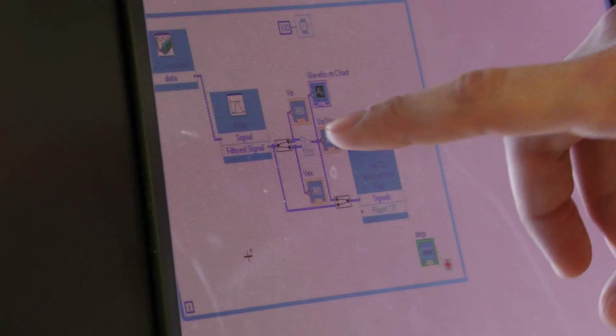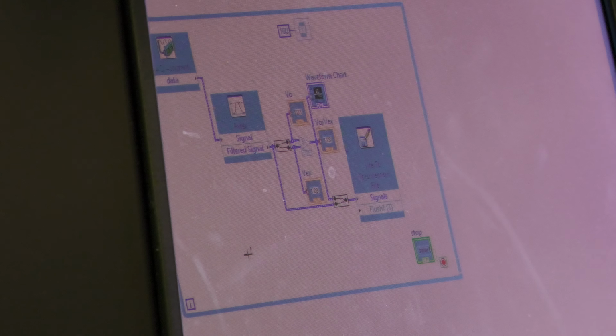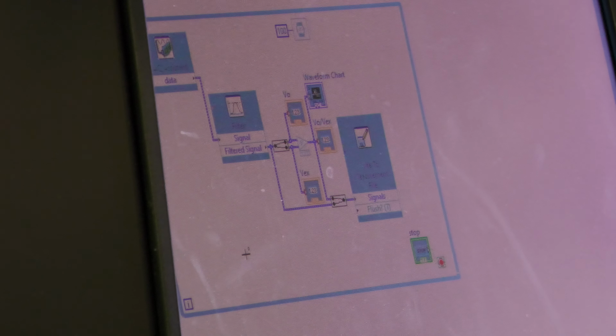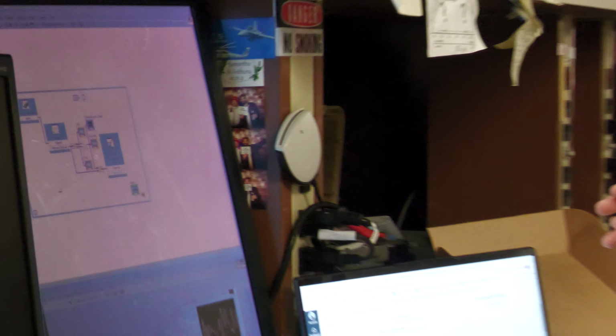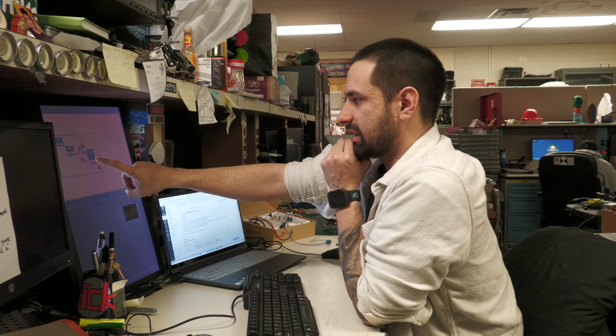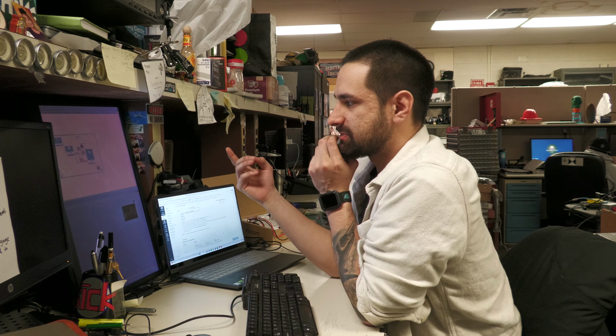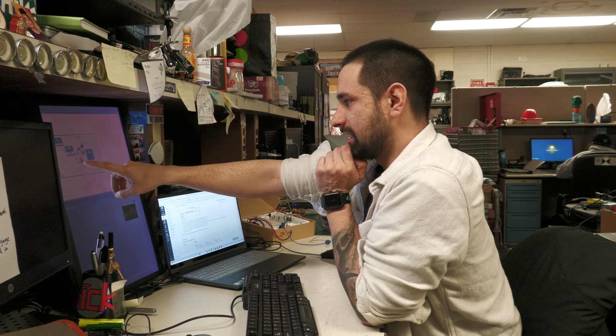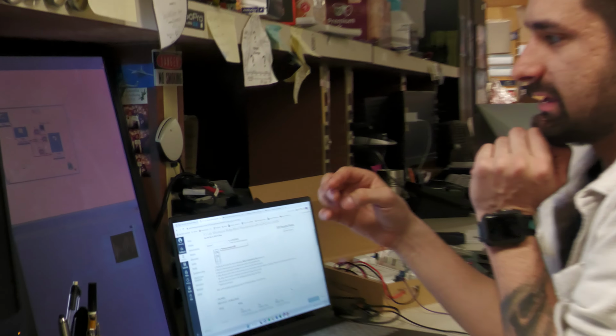Basically, in the block diagram, we have the DAQ Assistant that is getting the signal from the load sensor, which is connected to the Wheatstone bridge circuit. From there, we're going to filter out highs, so we're going to have a low-pass filter. From there, we are going to use that data and write it to an Excel file, as well as split that data into Vout, Vex or Vexcitement, and then finally the output, which is VO divided by Vex.